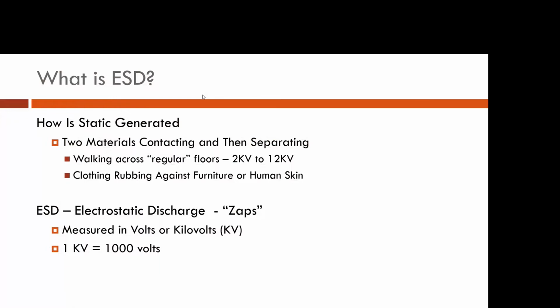Anytime you pick your foot up off a floor after you've touched it, there is a certain amount of triboelectric charge that is going to be built up. And depending on the type of material that the two surfaces are that separate, really pertains to how much electrostatic discharge static electricity is created. For instance, if you have two pieces of rubber pulling apart, they're generally insulative and they're not going to create a tremendous amount of electrostatic discharge. Versus if you had a feather and Teflon, they would create a tremendous amount of electrostatic energy.